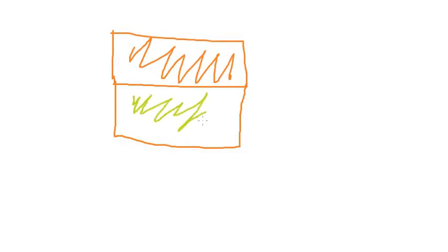Let's say in your research paper or reference paper there are given coordinates that you have to make it this much thickness. You can understand it like this: if it is given that you have to make a 1 micrometer thickness. As I told you, in Silvaco all our coordinates are in micrometers. So if you write 1, it means region x.min is equal to 0 and x.max equal to 1. That means 0 micrometer and 1 micrometer.